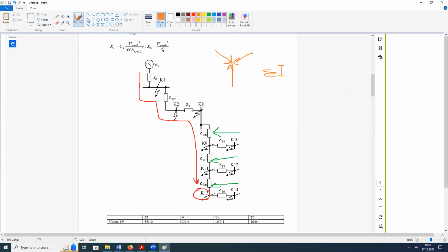I need to calculate the K13 and calculate the sensitivity for the lines that go in series. For example, you could check number 9, number 11, and number 4, 13. Say if number 9 is okay, so yes, this protection is feasible, but the question is how sensitive this protection could be. If it is not sensitive for K9, the set point is wrong, you should choose another one.